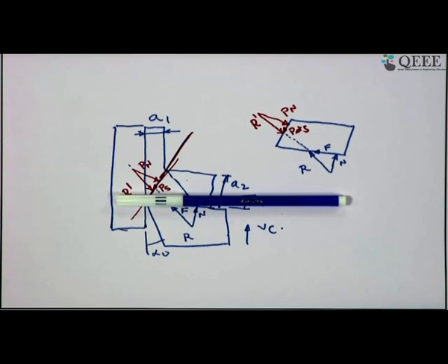So, anyway, we have to keep in mind that the Py component should be as small as possible, or the rigidity of the setup should be such that the Py cannot make such kind of local elastic deformation, which ultimately leads to an inaccuracy in the job dimension, in particular on the diameter. So, I think this is understandable.